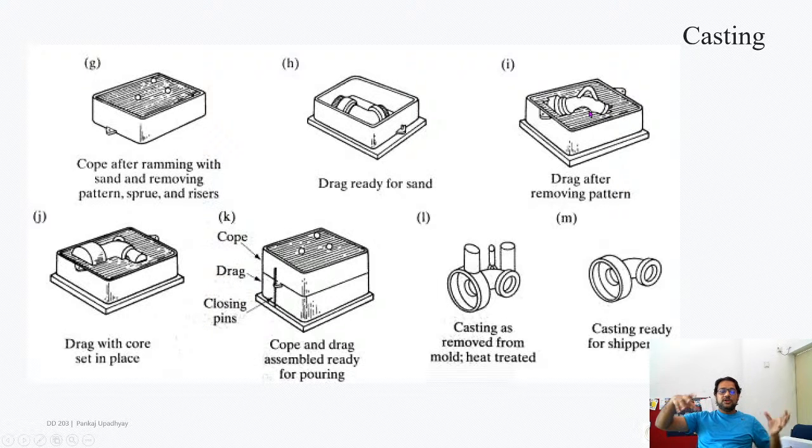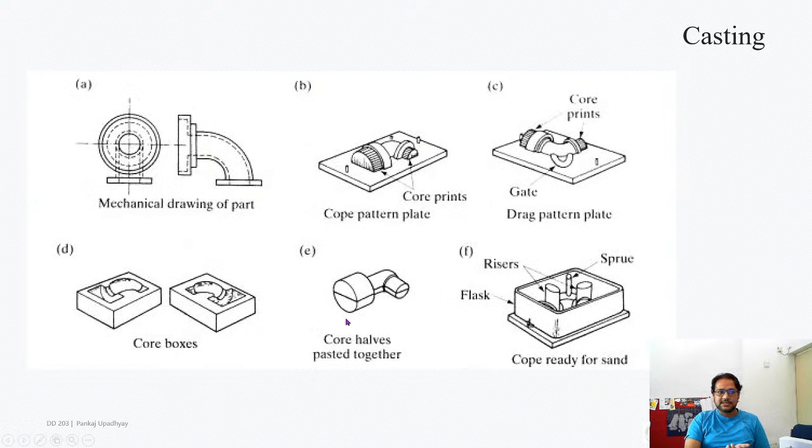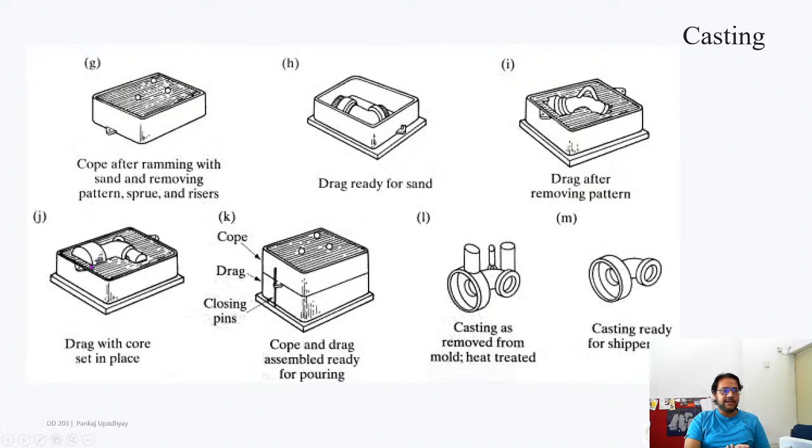Okay, so I made the slingshot pattern exactly as it is, and to the point where it is divided just like this, and now in that I place this. This small thing I place inside that cavity of the pipe which is created, and now when I close it, I am sure that the places where that core was there, the molten material would not travel there.